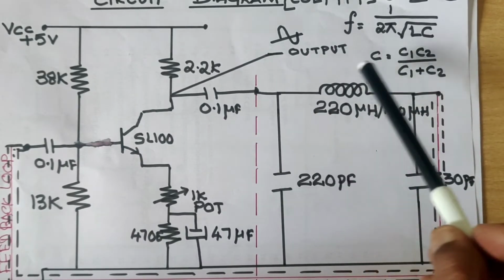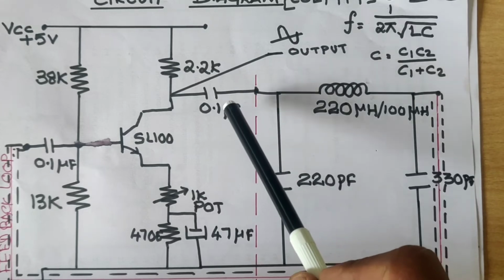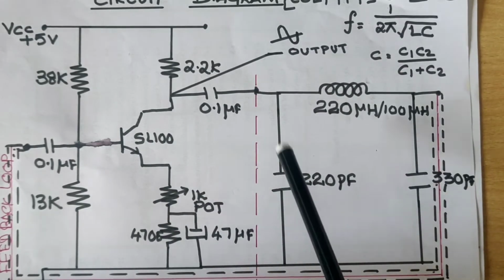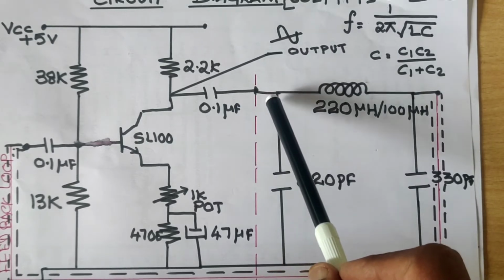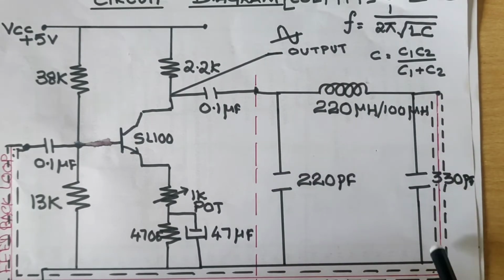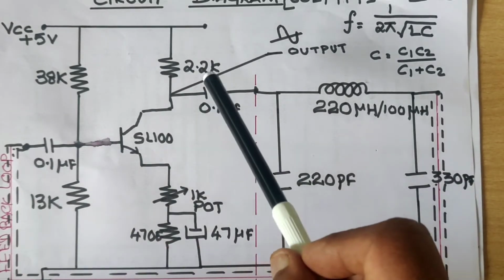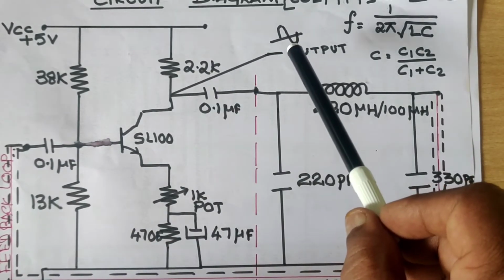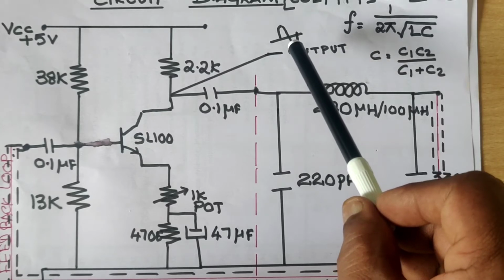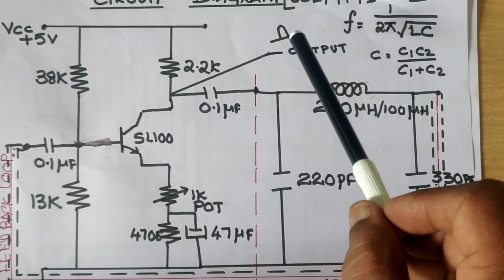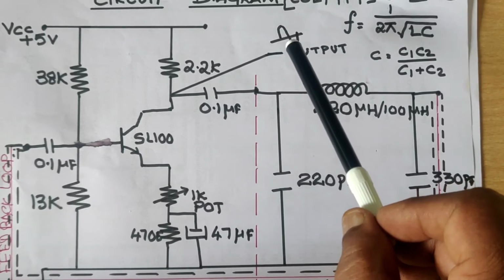Now after connecting the tank circuit, we are supposed to connect this part, because we made this into two parts, amplifier and tank circuit. So this connection is very important. In addition to that, we have to complete this loop, this part, and connect the CRO to the collector part, and you can see the output and undamped oscillations and calculate the frequency and amplitude.